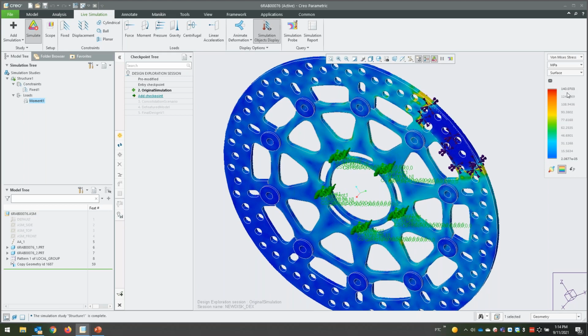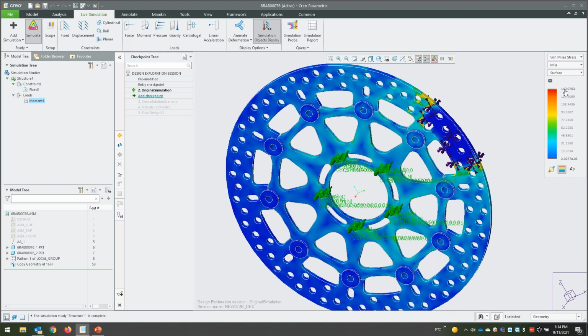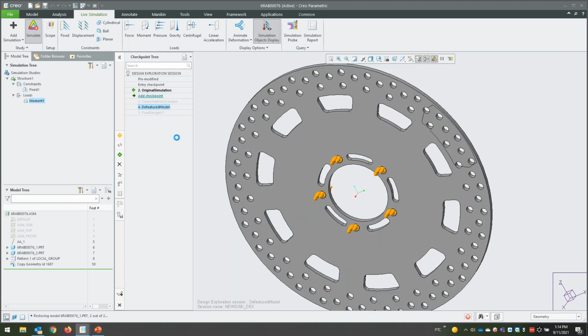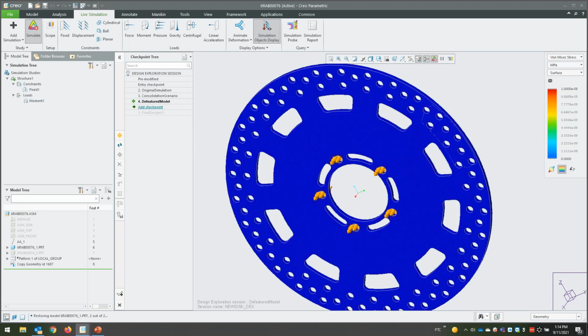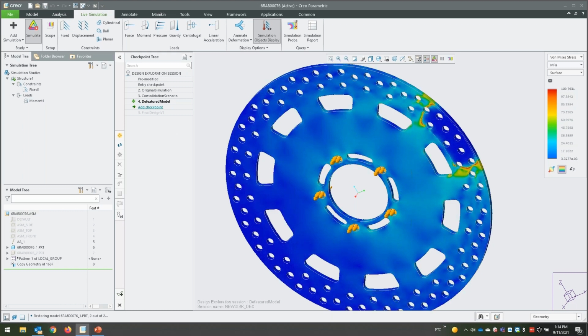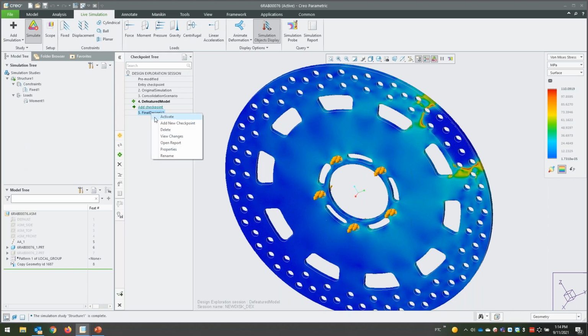And so looking here around a value of 140 megapascals for this particular design based on the loads and constraints and materials placed in. If we go and look at a different variation of design. So imagine we've gone back, we've changed our design, we've done this, we've done that, and we come back. And then the analysis, I didn't need to press anything here, it just updates, okay? So now we're down to roughly 110 megapascals.